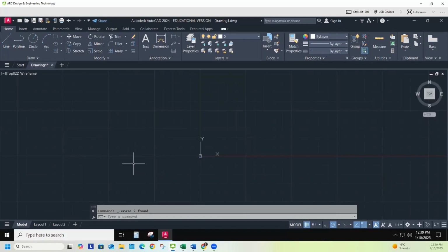All right, and then down here, this is the status bar. The status bar has some very useful tools, and these will affect your drawing area. For example, it can affect the display. If I turn this grid on and off, I could do so like this, and now the grid is gone. The grid is there. There's also ortho mode and polar tracking. These are very convenient things. Object snap is located here. This has a lot of very useful tools, which we will go over.